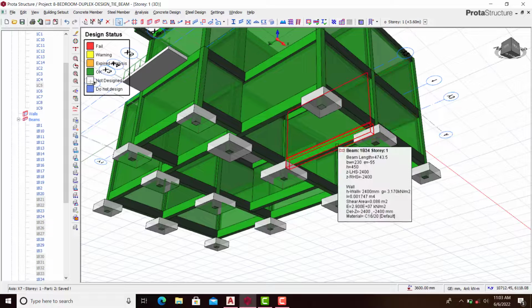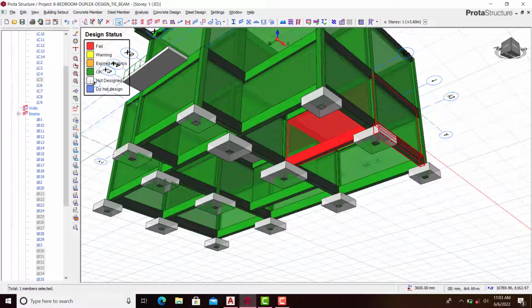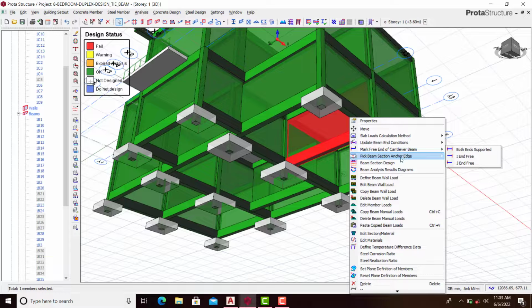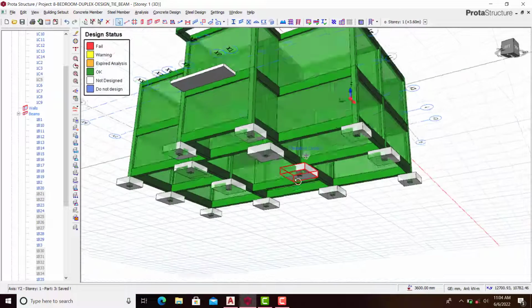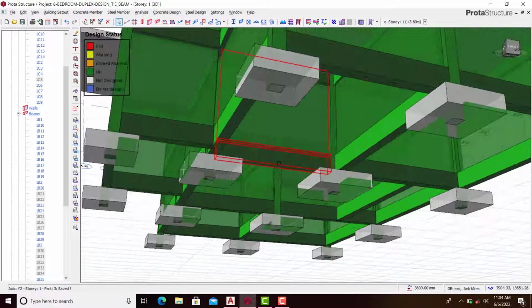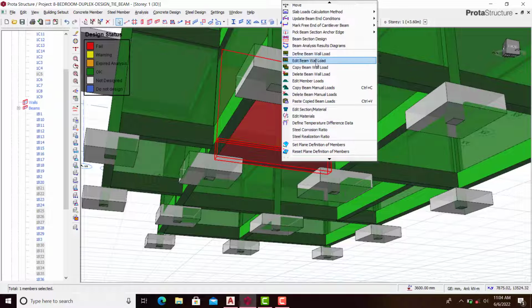We just rotate to look at this building from under to check our internal beam. So you can see how stressful it is going to be to check the beam one after the other. That shows you how important it is. It might look stressful, but it's very important to know the kind of reinforcement that the software gave you for your beam designs or for your concrete member designs. So you go on this to check this.